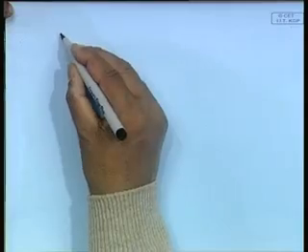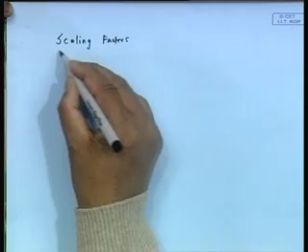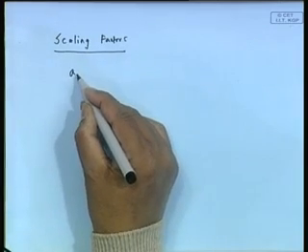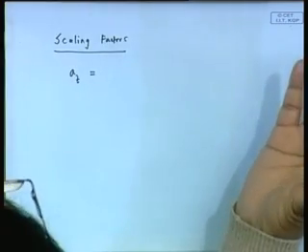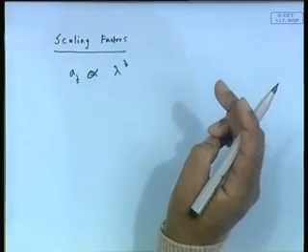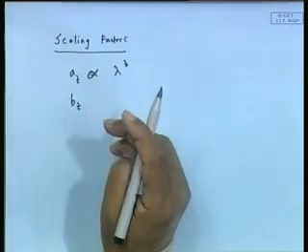Now, of course, you are doing a scale test, you are not doing a full scale test, you cannot have a full scale ship doing a test. So what is the scale factor? Another point that I should explain is scaling factors when I do a measurement. Added mass will scale at what? See, added mass is proportional to mass, so obviously it will scale as lambda cubed, right? Tell me how damping will scale. This is important, I want to tell you this.